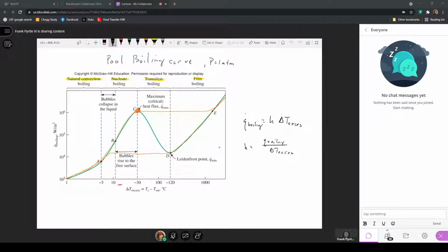When we consider this film boiling, we're considering that there's a vapor blanket that actually separates the liquid fluid from the solid surface where heat is being added. So instead of seeing Nusselt number correlations for boiling, you'll see actual expressions for heat fluxes based on the regime or the point in a regime where that expression of a heat flux is actually defined.